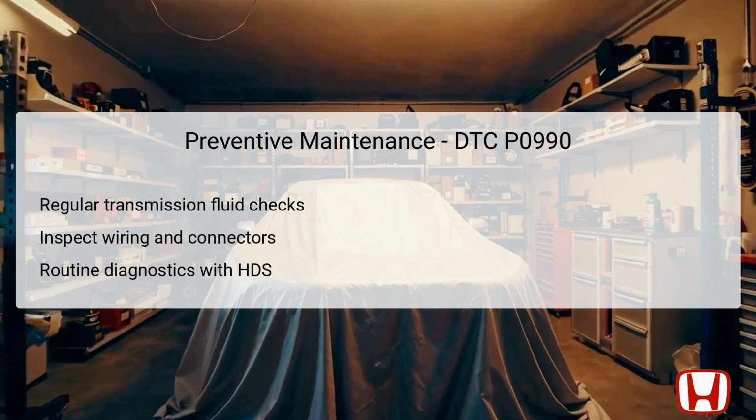Routine diagnostics using the Honda Diagnostic System, HDS, may flag issues before they escalate into major faults, giving a proactive approach to vehicle maintenance. By scheduling these inspections and maintaining a keen eye on both fluid levels and electrical connections, you can ensure the long-term health of the vehicle's transmission system, preventing unexpected breakdowns and costly repairs down the line.